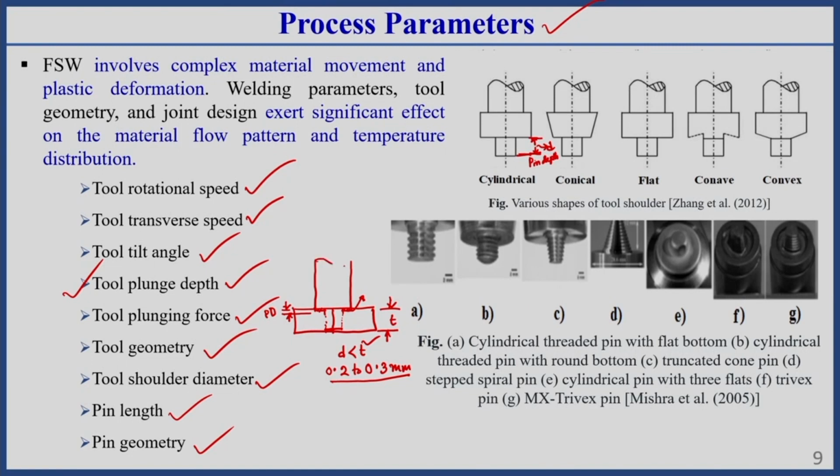What is plunging force? You see, this is the most important force. Plunging force is the vertical force acting on the tool, perpendicular to the plate surface, that you can observe. This is called plunging force. Depending upon this plunging force, which is a normal force, frictional heat is generated.